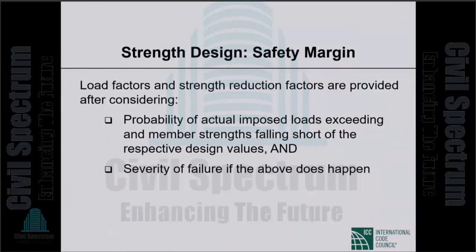Load factors and strength reduction factors are provided after considering probability of actual imposed loads exceeding and member strengths falling short of the respective design values, and severity of failure if the above does happen.